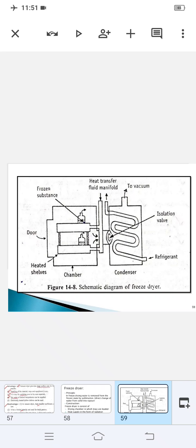Okay, so let us see what happens in the first step, preparation and pre-treatment. Means when the solution is introduced into the container, its volume is limited by the capacity. Okay, so satisfactory freeze drying beyond a certain limit of depth of liquid is not possible. So pre-treatment is essential. So what is happening here? The solution is pre-concentrated under normal vacuum tray drying, okay, and it will reduce the actual drying time by 8 to 10 times, and the final product becomes more porous, okay. So liquid or solid desiccants are also used for this purpose. So the preparation and pre-treatment step is done.